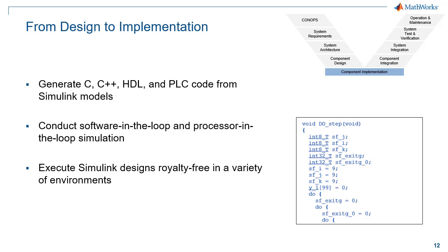Why would you want to do this? Again, you may want to be moving to an environment that MATLAB cannot be run on. But before you even get there, it may be important to verify that as you move out of the Simulink model and convert to code, things are still behaving as you expect, that nothing is lost in the automated translation to these other formats.